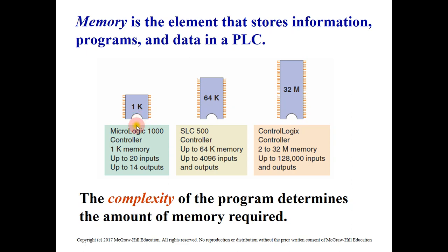In terms of the number of inputs and outputs, we can use 1K, or 1 kilobyte, with the MicroLogix 1000 controller. It uses 1 kilobyte of memory, which supports up to 20 inputs. That means I can connect 20 inputs, like 20 sensors or 20 switches, to the PLC unit, and up to 14 outputs. So if you have 20 inputs and 14 outputs, you can use the 1 kilobyte memory.